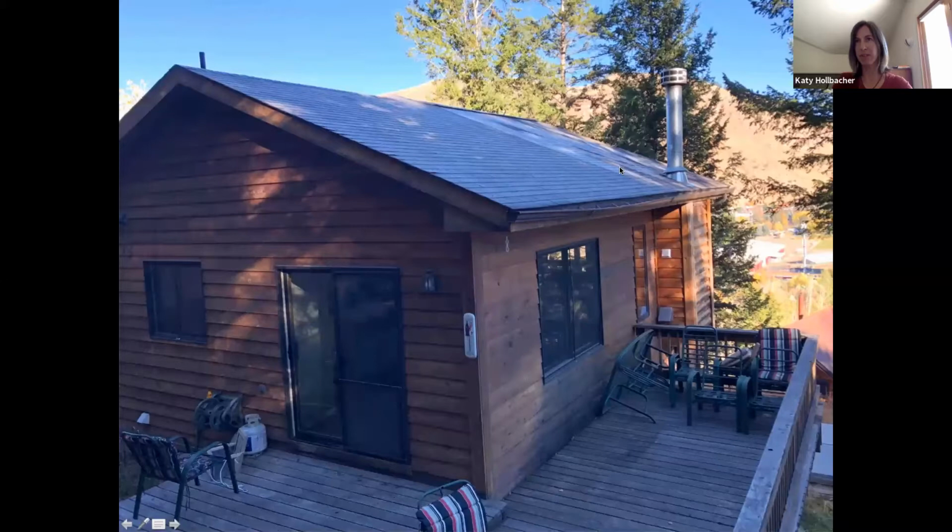So what's actually happening here? In a high performance roof, everything would have frost. This roof would be cold. It would not be letting heat from inside the home out. And in this case, there's clearly heat getting into this attic space that's supposed to be well insulated. You can see where there's foam that looks to be doing an okay job.